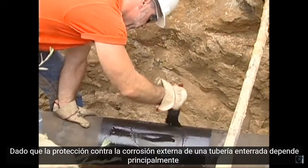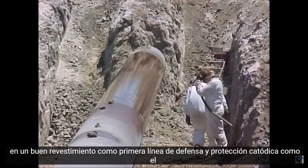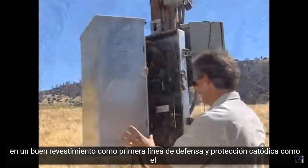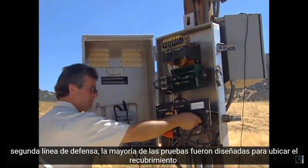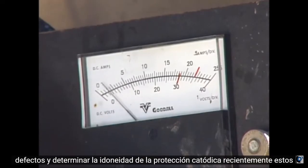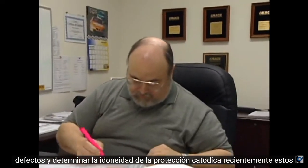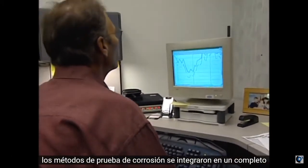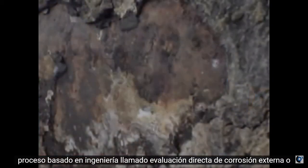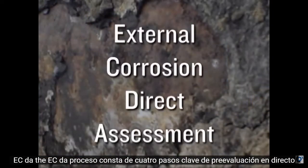Since external corrosion protection of a buried pipeline is primarily dependent on a good coating as the first line of defense and cathodic protection as the second line of defense, most of the testing was designed to locate coating flaws and determine the adequacy of cathodic protection. Recently, these corrosion testing methods were integrated into a comprehensive engineering-based process called External Corrosion Direct Assessment, or ECDA.